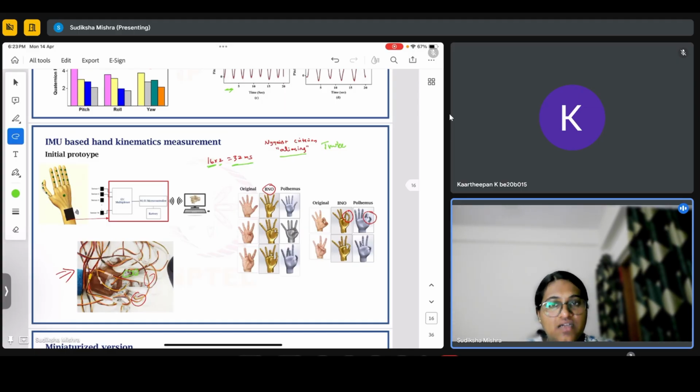If your sampling is done at least twice the highest frequency, then the system qualifies for the Nyquist criterion. If it does not, it falls into the problem of aliasing, where the information is generated at a very high frequency, but the sampling is not done at that frequency. Because of this, you lose out on some data.